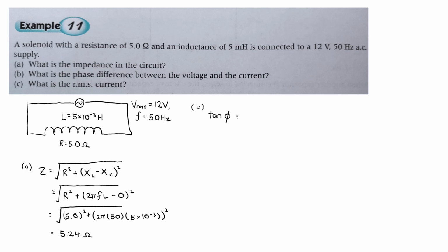And we know tangent phi here can have a few different versions. You can take the peak current for the inductor minus the peak current for the capacitor divided by the peak current for the resistor. But if you look over here, there's no info on the peak voltage for L, C, or R. So I believe it's another version. There's also an RMS version, but I don't bother to write it down because you know that wouldn't work either.